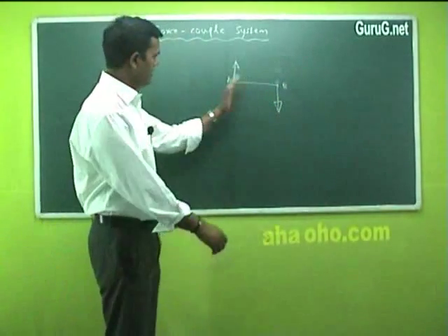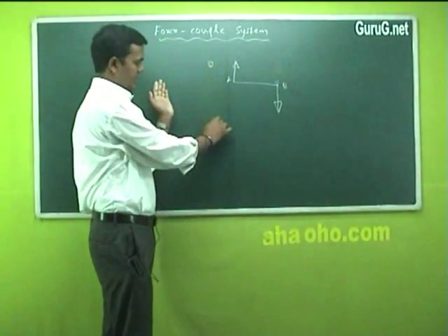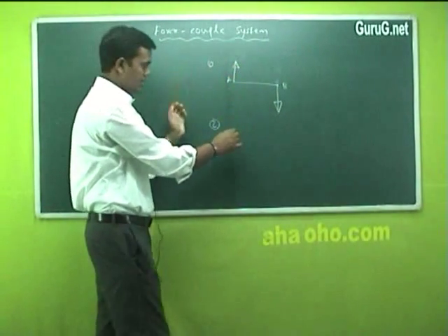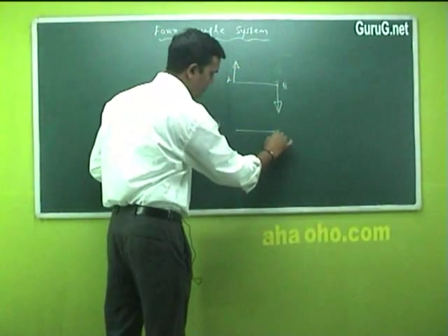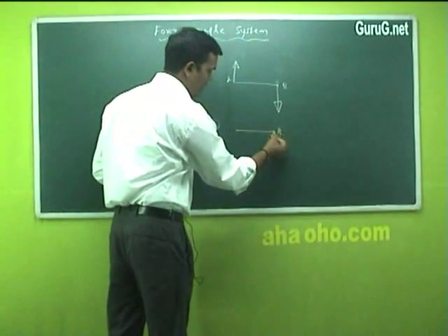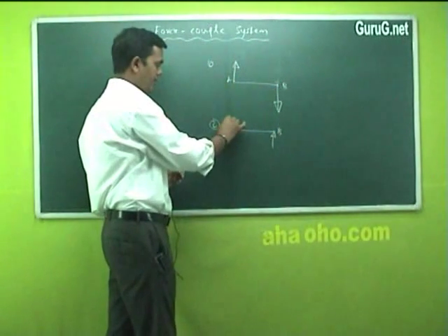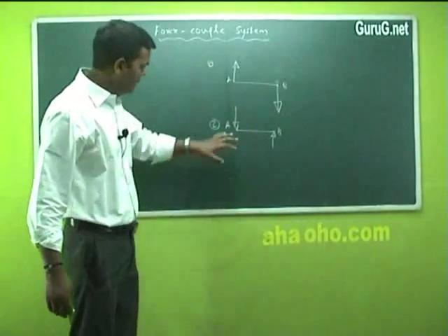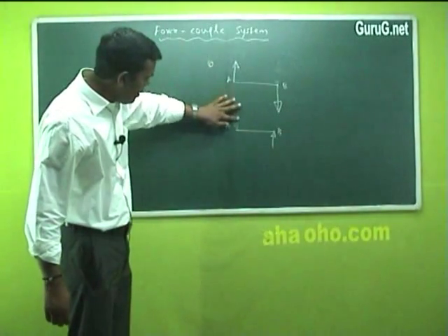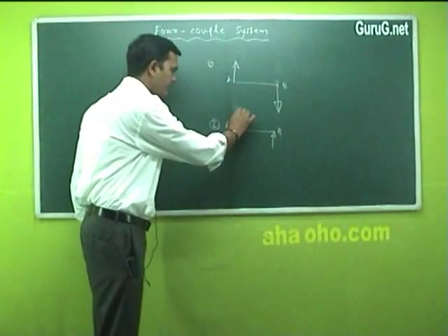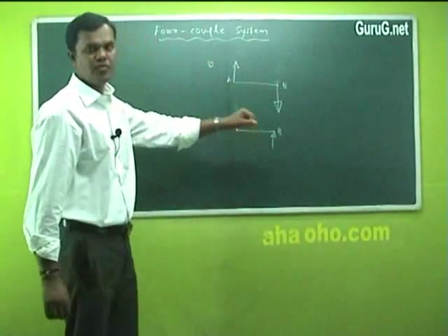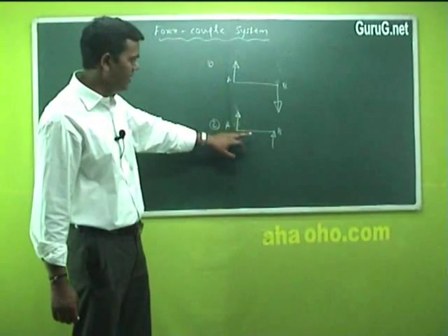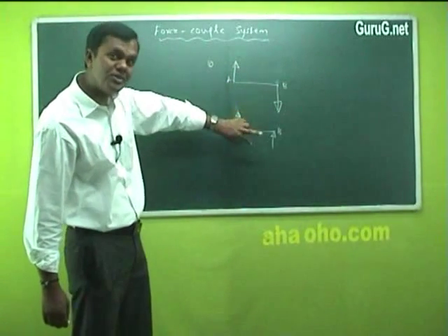Okay, this is one diagram. In the second diagram I can indicate the same parallel forces acting in opposite direction. I can take one force acting at point B upwards, and at point A I should draw it downwards. If at point A I draw a force which is also up, this will not form a couple, because a couple should have directions in the opposite sense.